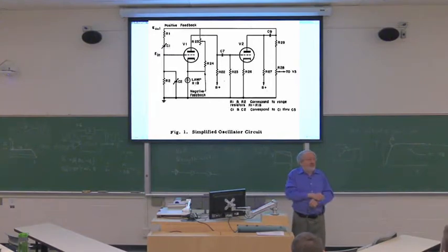How many ohms will it read? So 1 amp. The light bulb says 120 volt, 120 watt, so it means it draws 1 amp. So 1 amp at 120 volt, if you measure it with an ohm meter, how much would it read? Okay, so you're saying 120 ohm.